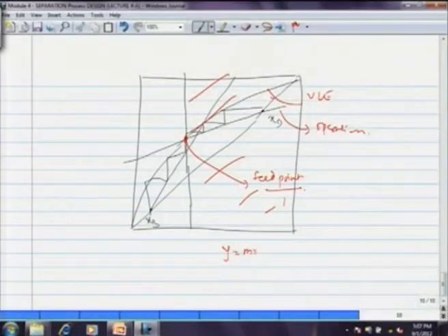You can apply exactly the same expression for the lower section of the column, the stripping section. However, you have to be careful about the values of m and b. Here you have learnt the determination of the equation of the operating line for the stripping section in the course on mass transfer. So, use that m, use that b for the stripping section operating line, and follow exactly the same procedure, okay, and then you will get the number of plates.